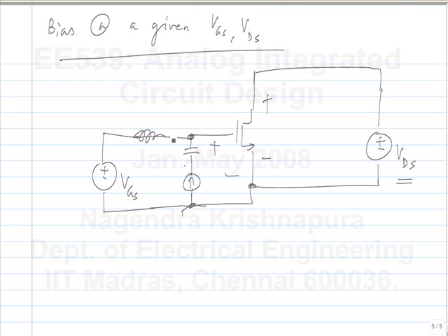What will be the value of the inductor and the capacitor? So first of all, let's say I want to measure the frequency response from some F min to F max. Okay. Clearly, I cannot measure it at DC because at DC this is open. So I have some minimum frequency that is not 0 to some maximum frequency.